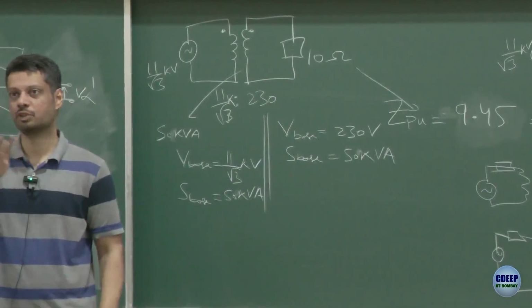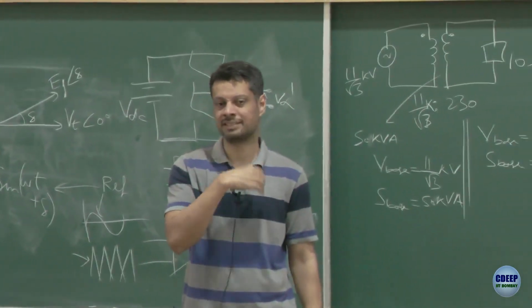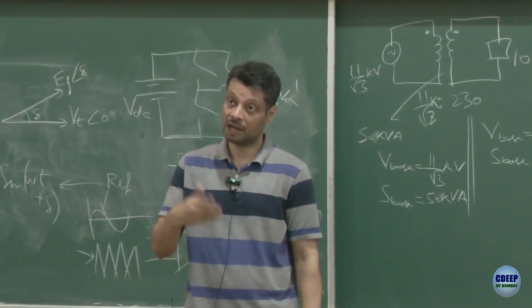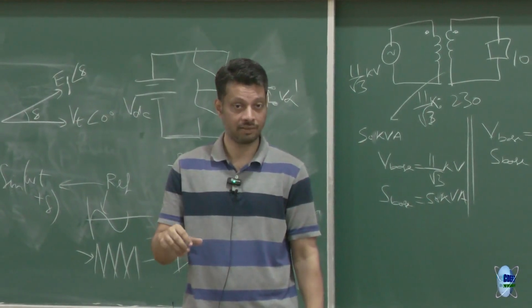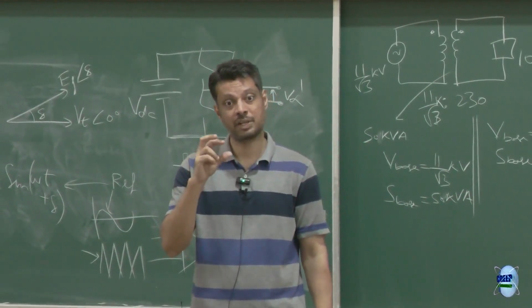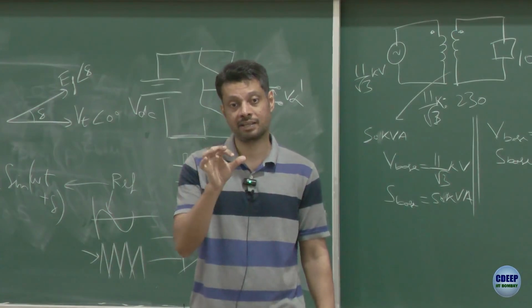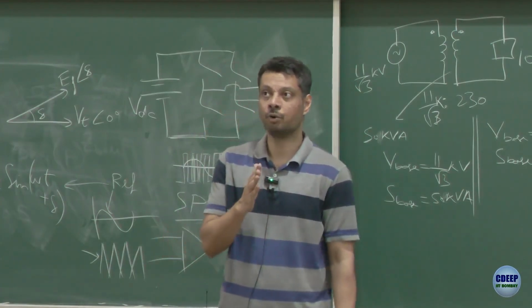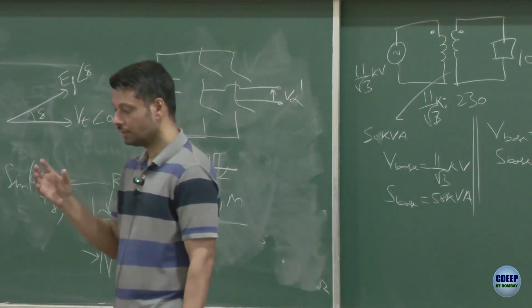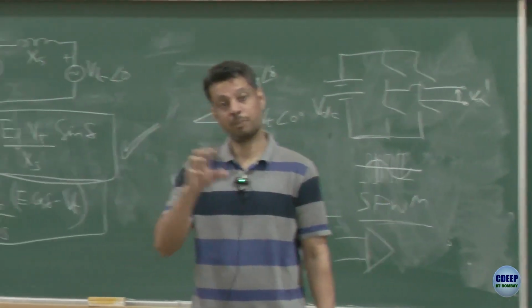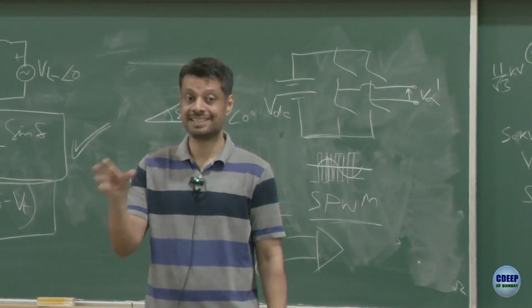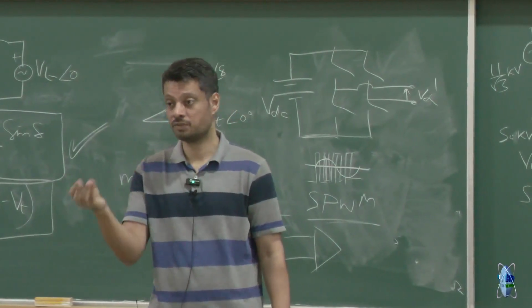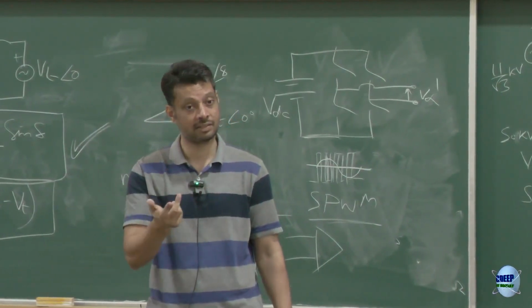Initially it was of course not possible. Fixed capacitor, fixed inductor, everything is fixed. Now, since you have more power electronics, you can, for example, switch a few inductors and capacitors on and off. There is a whole range of devices which are a combination of passive devices and some active devices, maybe MOSFETs, IGBTs, or thyristors.